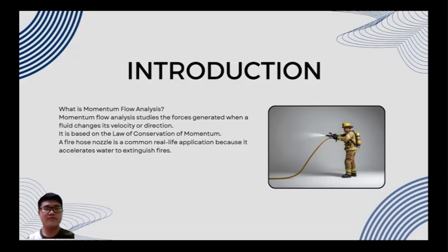Our application focuses on momentum flow analysis. Momentum is the product of a fluid's mass and velocity. When the velocity or direction of a fluid changes, its momentum also changes. This change in momentum produces a force, which is explained by Newton's second law of motion. Engineers use this principle to calculate the force acting on equipment that carries moving fluids.